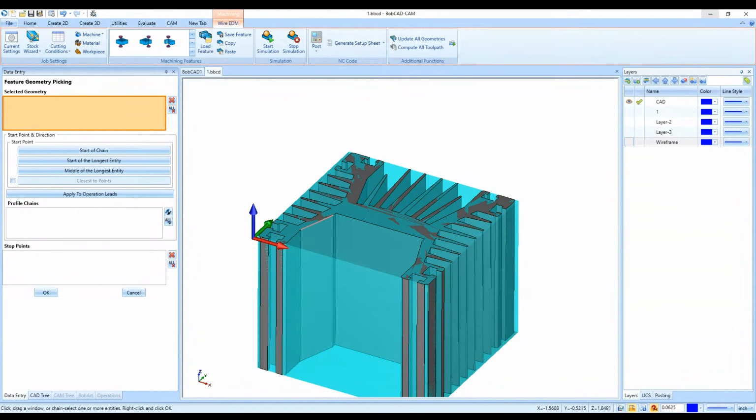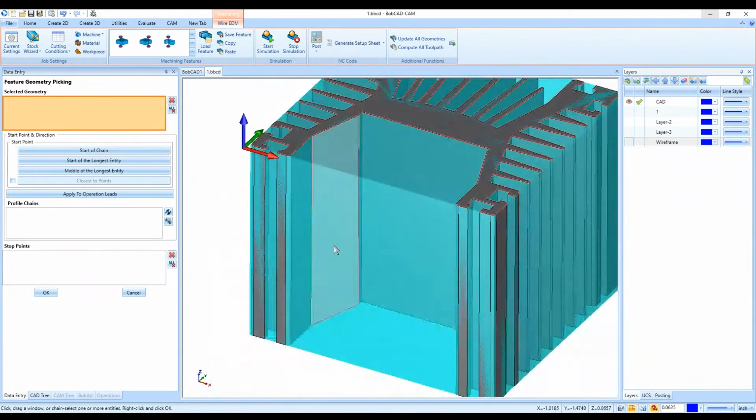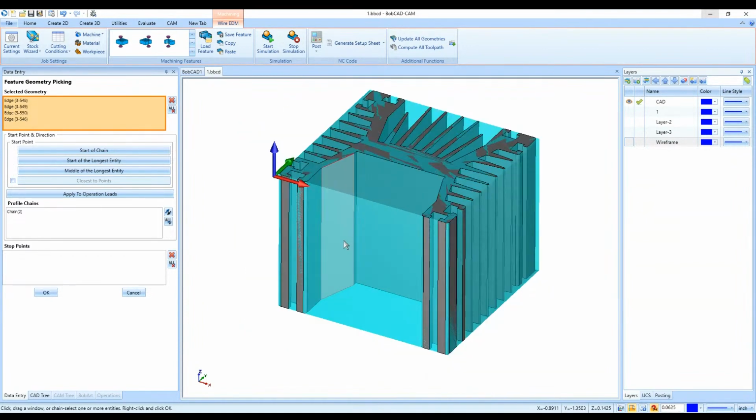We also have loop selection, where you can see all of the same entities are highlighted, and these 4 entities on this surface are highlighted as well. All these 4 entities are highlighted also. So if I select one of these 4 entities, it'll pick up the rectangular shape, thinking that I want to cut out this rectangular surface shape. Or if I go back to loop selection and select one of the entities going along this chain selection, it'll chain select all of those entities for me.